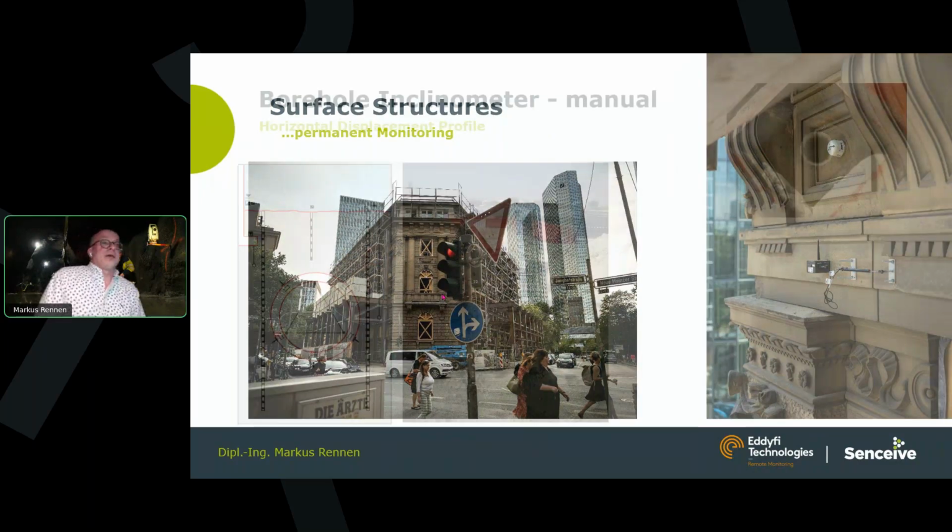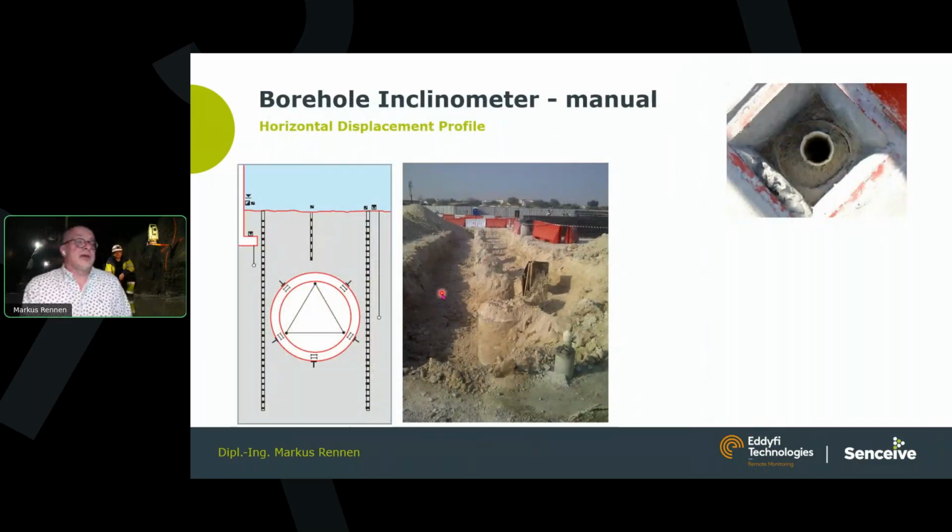Well, coming back to immediate tunnel impacts, this could also involve different kinds of sensors. So departing from the geodetic observations, we come to the geotechnical part, where, for example, we have pipe drillings here, where borehole inclinometers are inserted.